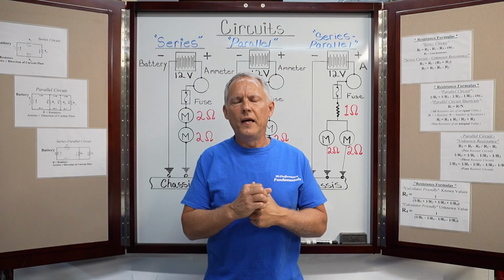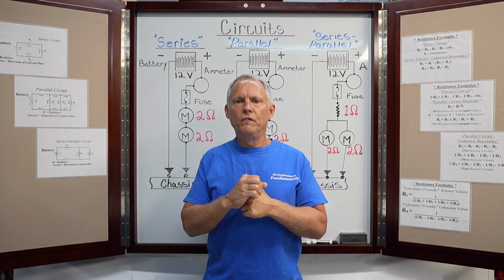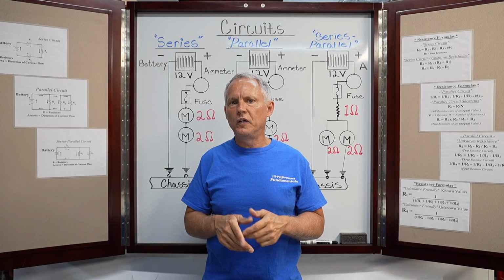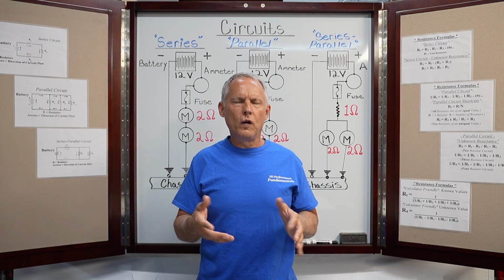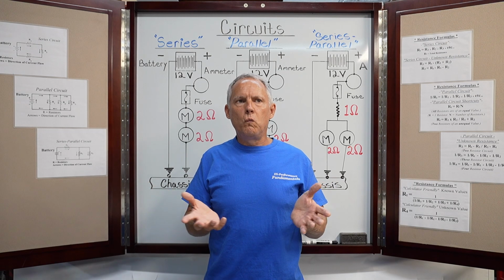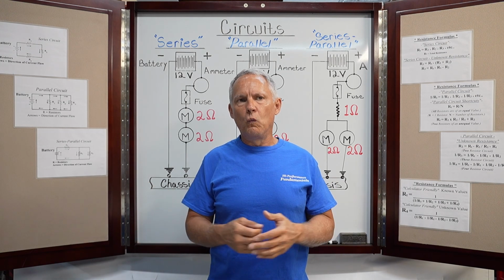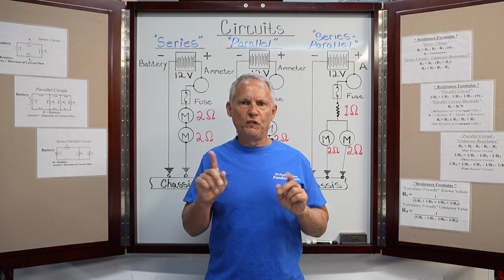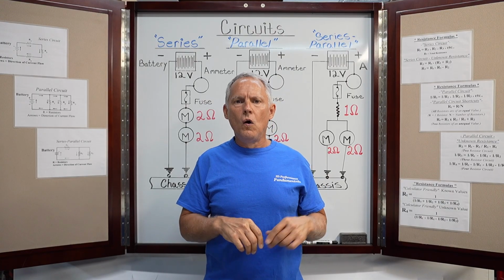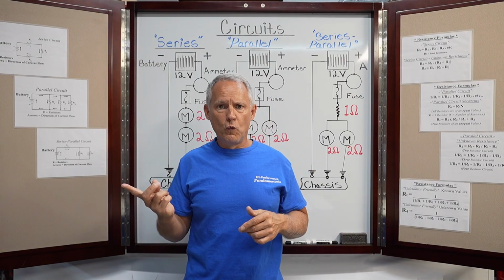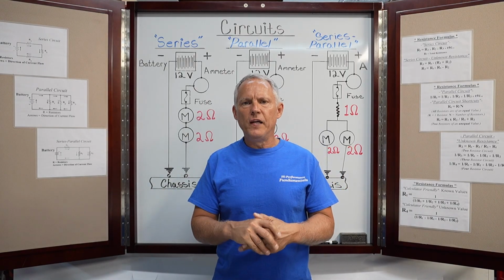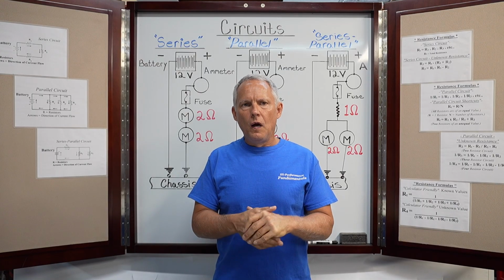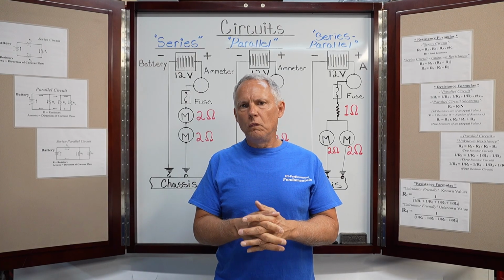All right, now with that being said, close to the end of the video, I mentioned point type ignition systems, and in particular I mentioned adjusting dwell. The information that I provided there was accurate, except for when I gave a range of specification for adjusting dwell on a V8, a 6-cylinder, and a 4-cylinder. The adjustment range that I had given for the V8 was 28 to 32 degrees. In most applications, that is still, I'll stick to that.